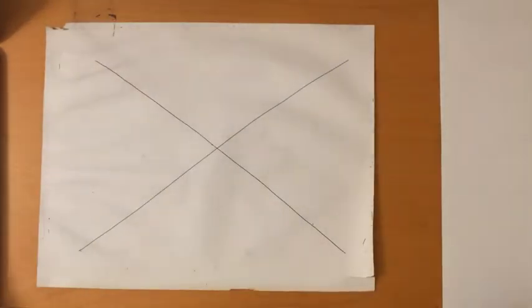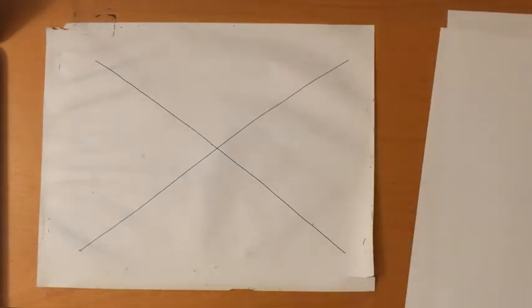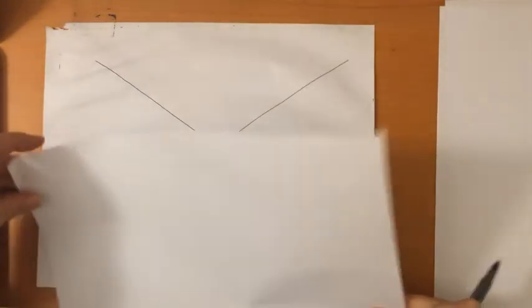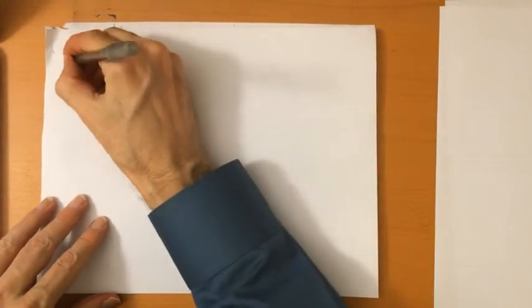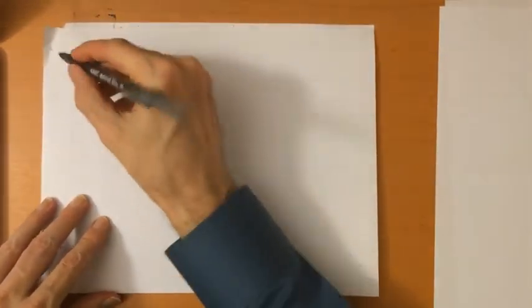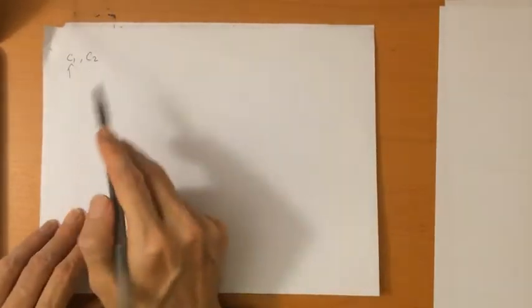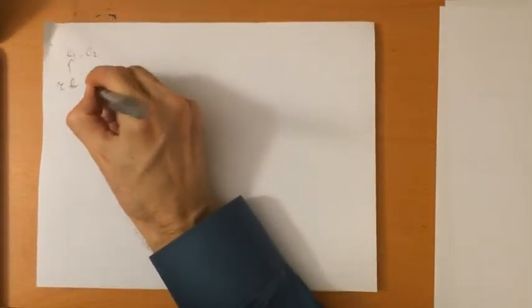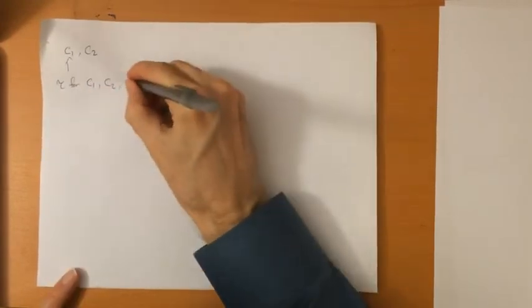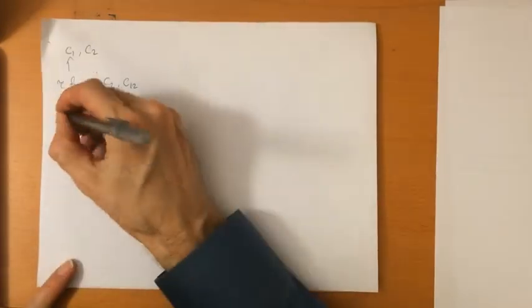And so what's going to happen with part C is, we've actually got two capacitors, C1 and C2. So we're going to be doing most of our work with C1 here. But when we go to measure the time constants, we're going to measure the time constants for C1, for C2, and for C12, which is basically the parallel combination of 1 and 2.